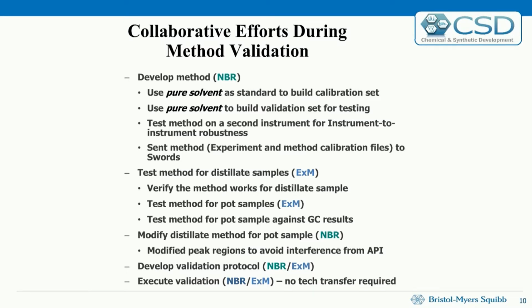One of the things that I had mentioned in the earlier slide was this data calibration and then transfer of a method, especially if it's going to go into a manufacturing site and it's going to be filed. So we'll go to an external site or external manufacturing site, and we will co-validate. It's something we've worked on because it's a lot easier to do a validation and divide the work. It's a lot easier than transferring, let's say, an HPLC method where it has to be revalidated in the new site with a column. The tubing can change. Hopefully they have the exact same instrument, the flow, the sensitivity of the diode array detector or fixed wavelength detector, whatever they're using, or refractive index.